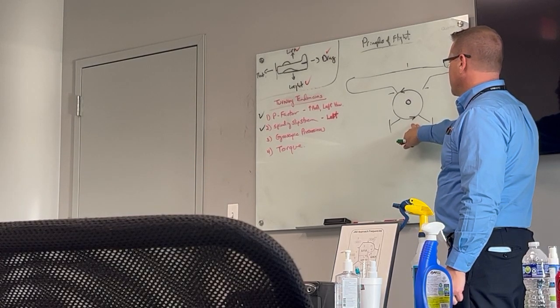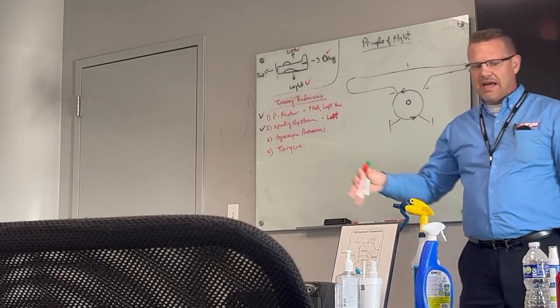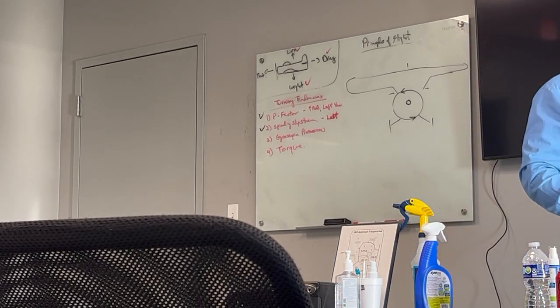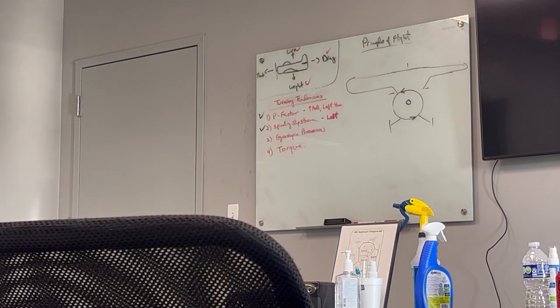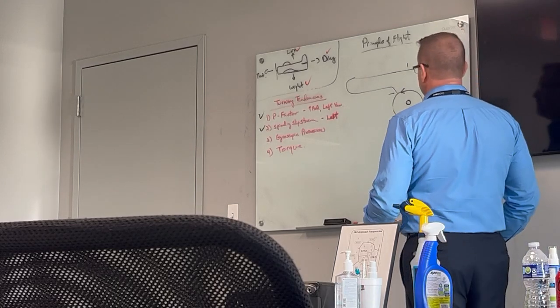One thing about a gyroscope, though, is that the actual resultant force is felt 90 degrees along the path of rotation from where it's actually applied. Okay, it's felt 90 degrees along the path of rotation, further along than where the force is applied.